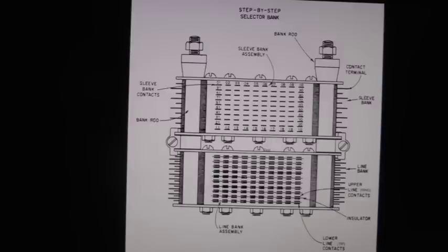However, their arrangement is such that the tens digit corresponds to the bank level number and the units digit corresponds to the bank rotary position number. Rotary positions are numbered 1 through 0 from left to right. For example, telephone number 11 is located on level 1, rotary position 1, while telephone number 00 is located on level 0, rotary position 0.